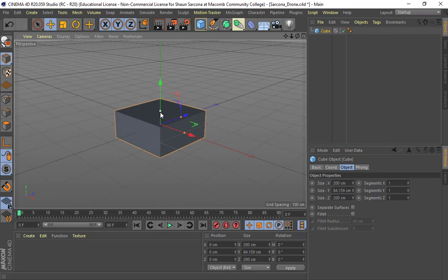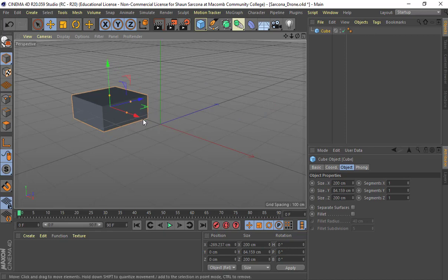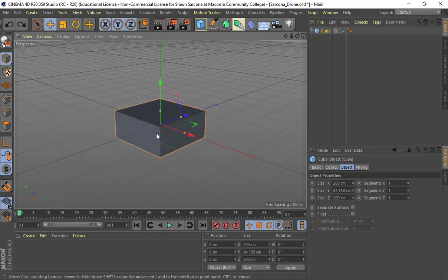As you model anything that you're trying to get symmetrical, never move it away from the origin, okay? I never want to grab this and pull it up or pull it back or pull it that way. I want to keep it exactly there. I can change the scale, the proportion, that's fine, but if you move it away, it becomes more difficult to set all the other stuff up.